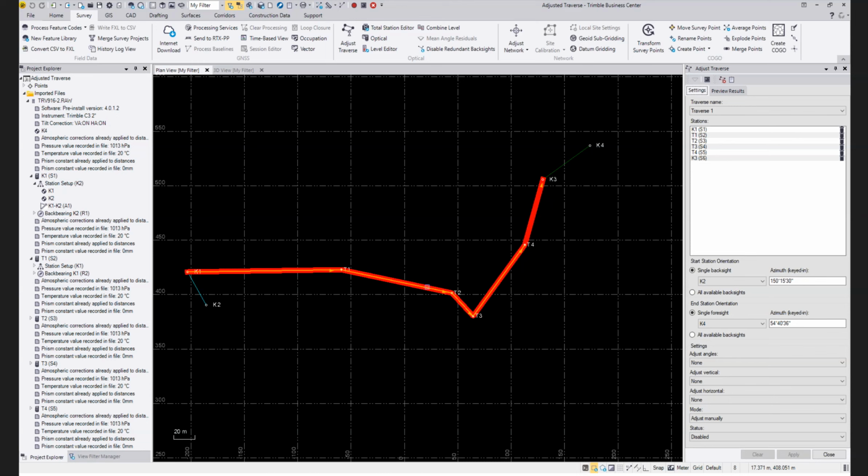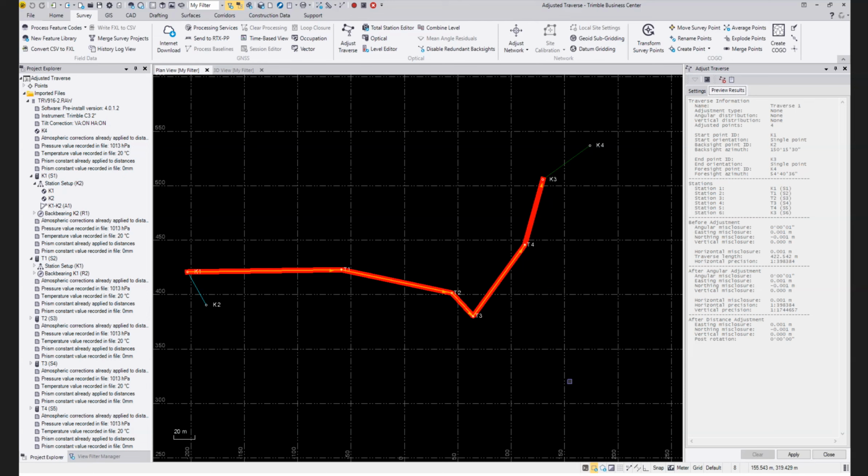It shows you the direction of travel of basically how it was collected, and allows you to change the members of your traverse and change any other parameters that you would like to see to impact the traverse adjustment. Maybe you change coordinates on some of your control points, or maybe you've decided that one of your targets was a different kind or something. You made some kind of change that would impact your traverse adjustment. And before you even make some changes here, it will automatically show you the results of the traverse